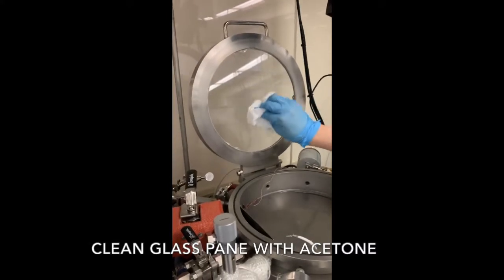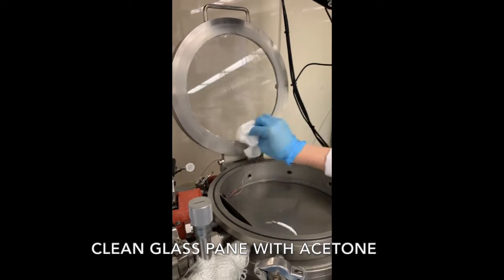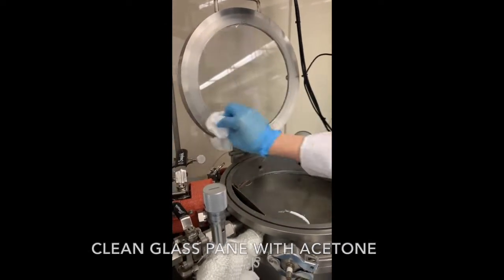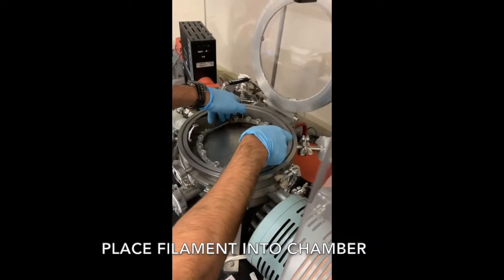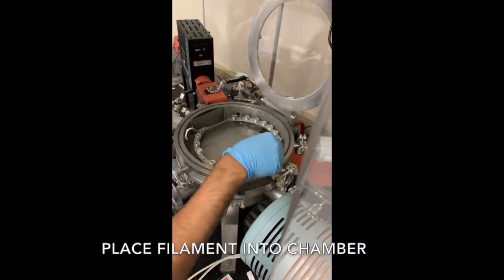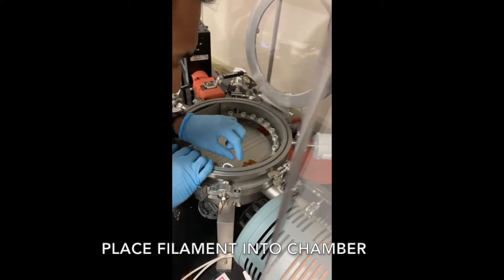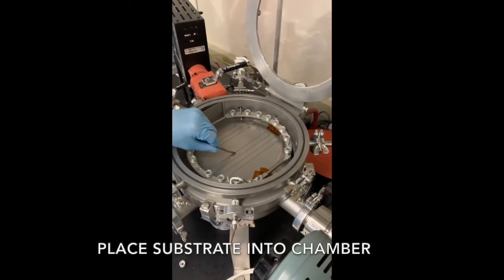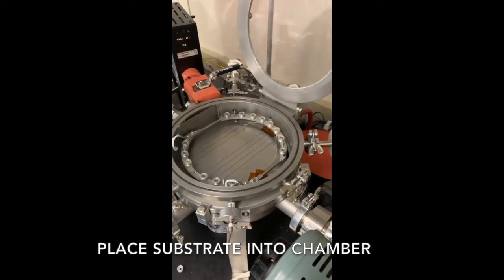The next step is to clean the glass pane with acetone as well. Any remaining film can affect the interferometer reading, which is later used to calculate the rate of deposition. We then ask the TA to place the filament into the chamber. Then you place the substrate into the chamber, making sure it's centered and that the laser refracts right into the sensor above.